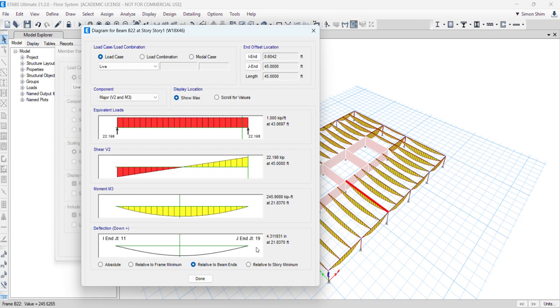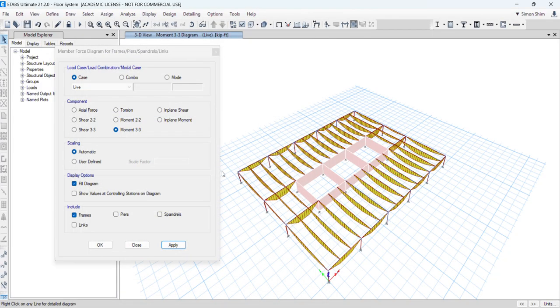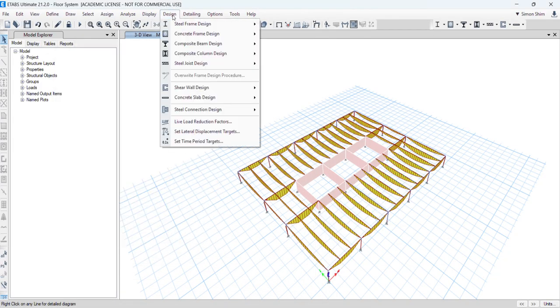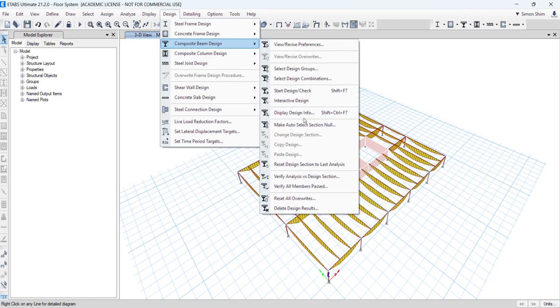So I want to make sure that you look through it and properly address your beam design calculation. So we're not looking at these beam deflections. This is pure steel beam deflection here. For the only deflection you should check, you need to run composite beam again.